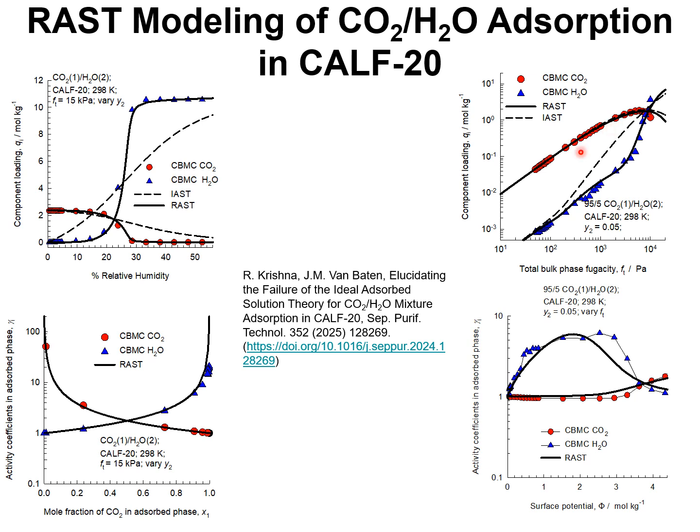From the CBMC data, the activity coefficients in the adsorbed phase mixture can be backed out, as explained in this article of mine. For the two sets of CBMC simulations, the adsorbed phase activity coefficients are shown in this diagram on the left for this CBMC data set, where the activity coefficients are plotted as a function of mole fraction of CO2 in the adsorbed phase.